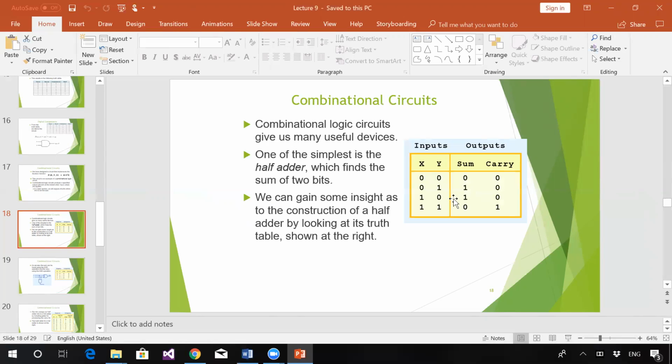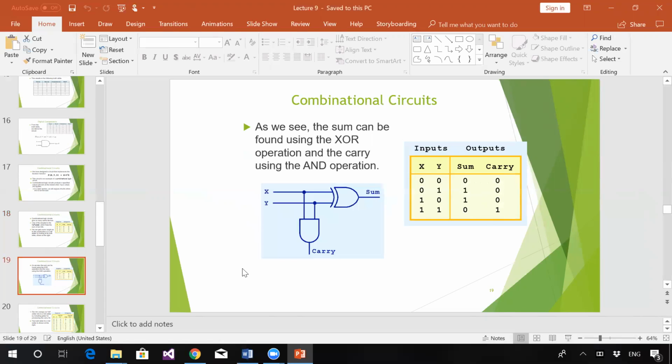As we know, for the adder, we are doing modulo 2 adding. We want a truth table like this, and if there is a circuit that could implement this, it is called a half adder. And in this half adder, if we also want to include another input, which might be the carry from the previous digit, it could be drawn as a circuit like this. So here we have learned one kind of combinational circuit, the half adder.